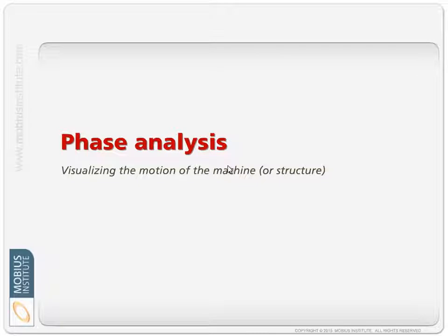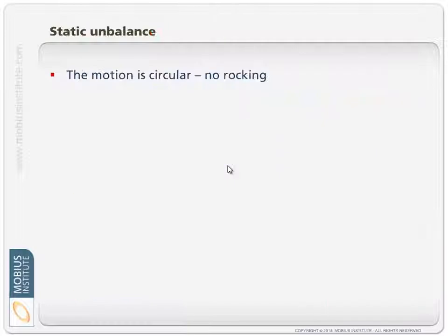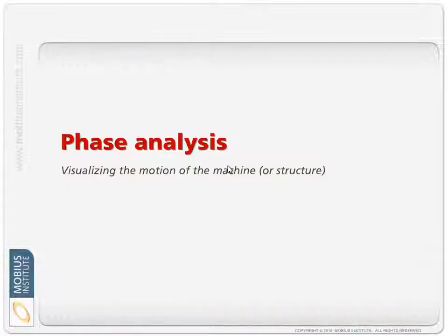There is another type of analysis we can do, which also adds information, and that's called phase analysis. Now, imagine, if you will, that the machine is out of balance, and we can think about that shaft trying to move in a circular motion, and we can think about the vibration it would generate. But think about the machine itself. This is potentially a high-ish speed machine, whatever, just 2-pole, 4-pole, 6-pole motor.